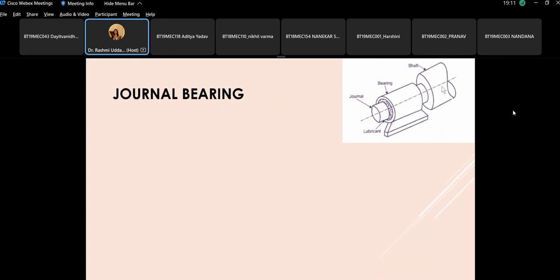So this is the shaft, and after the shaft there is a step down, another projected part with a slightly smaller diameter compared to the shaft. That goes inside this bearing, whose outer covering is stationary, and then there is this journal, which is a part of the shaft but not the shaft itself, since the diameter of the journal and the diameter of the shaft are different.